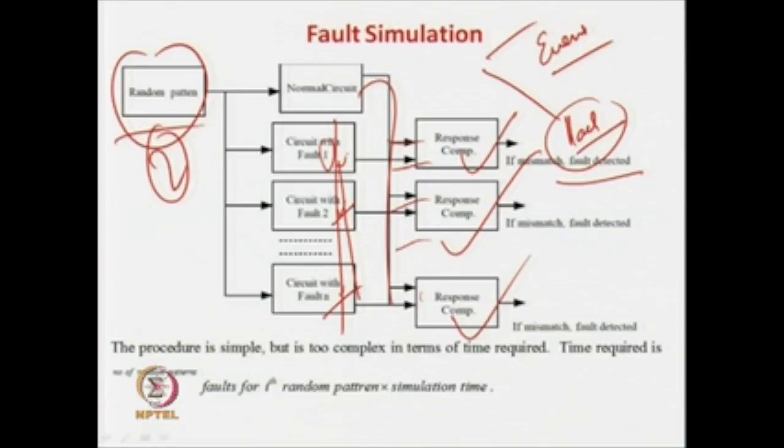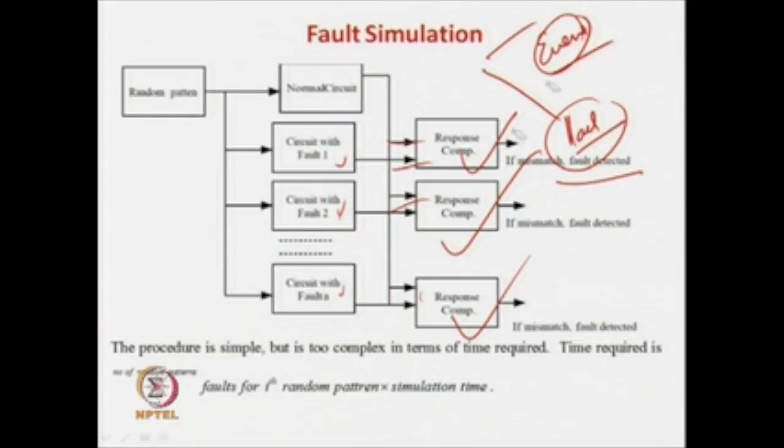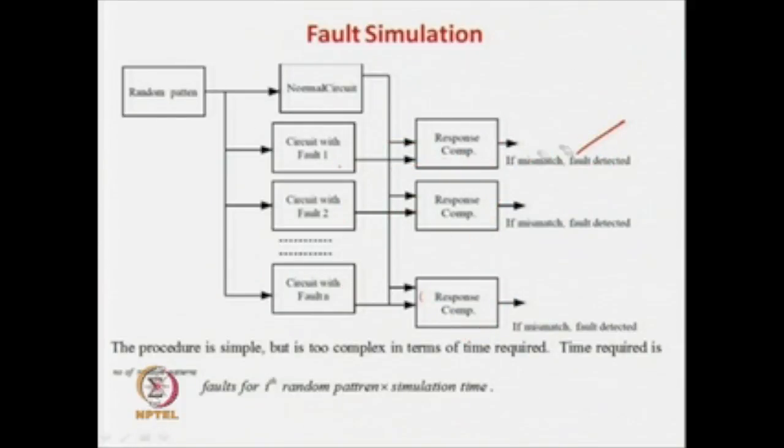That is one good way of doing it, and that is event driven, because if you are going for compiled code simulation, then even for a small change in the faults or the input pattern, you have to go for a full code simulation. So, these are the two factors we have to improve. One improvement is this event driven simulation and the other is parallelism. Both of them we are going to see in detail.